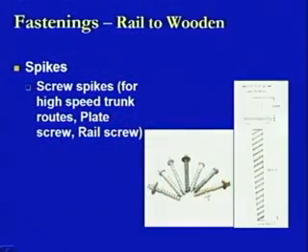In this case, these are again of a similar sort of condition, like as we have seen in the case of the bolts. This is the one diagram where the screw spike has been shown. Here, instead of the bolts, the only difference which comes is that all these screws are coming up to the top of this one, so that when it is inserted inside, then through this hole it will get connected to the topmost surface of the rail section, and still it will maintain tightly the fitting of that rail section with the wooden sleeper. So, there will not be any loosening effect because of this much amount of screwing being provided.